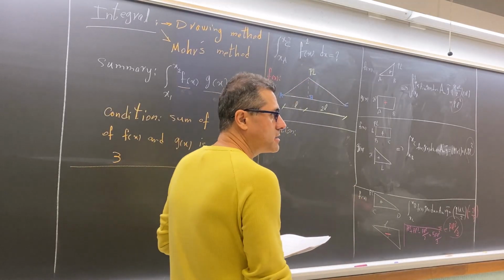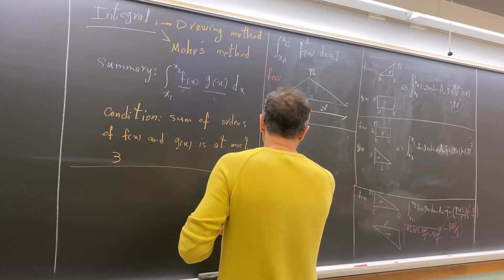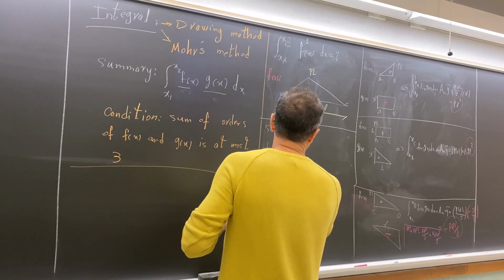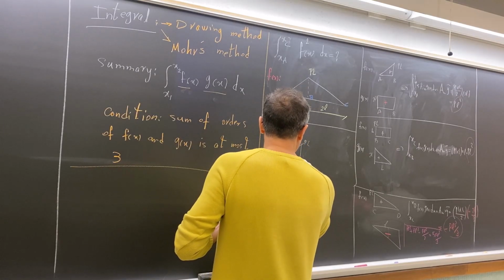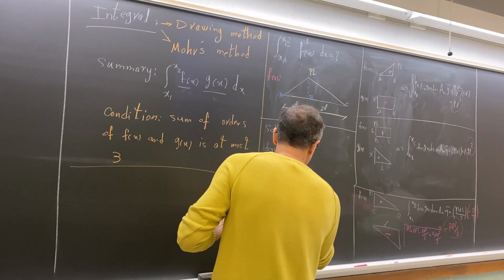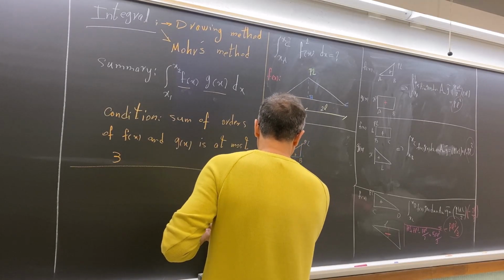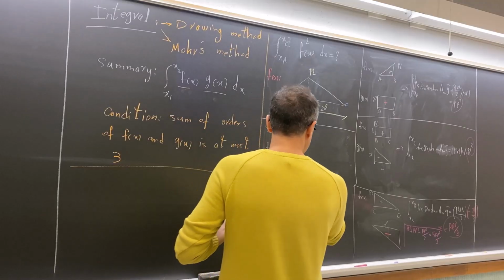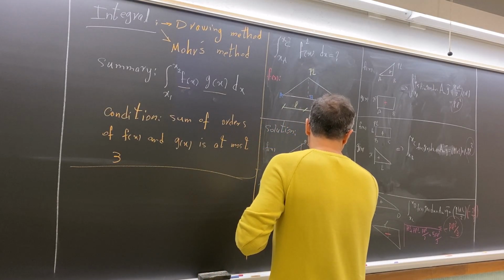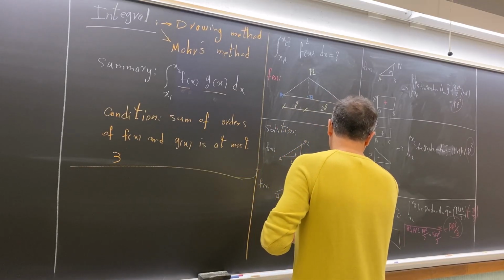g is f again here. F times f. So I draw the first part. This is PL, this is L, A, B, and then I repeat it because it is f times f. And it is positive, so y bar is positive. So from here, AM times y bar, PL times L over 2,